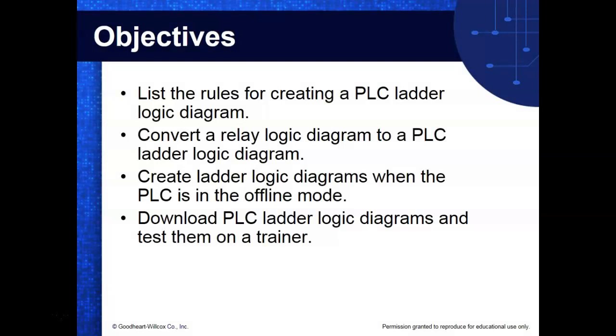So this is what we're going to do. We're going to learn some rules of PLC ladder logic programming. We'll look at converting relay logic diagrams to PLC logic diagrams. We'll look at creating logic diagrams when a PLC is offline, where we'll talk about the different modes. We have different modes we put our application in, and then we have different modes we put our PLC in. That makes sense. So when it says the PLC is in the offline mode, this is not exactly true. This is the application that's in the offline mode.